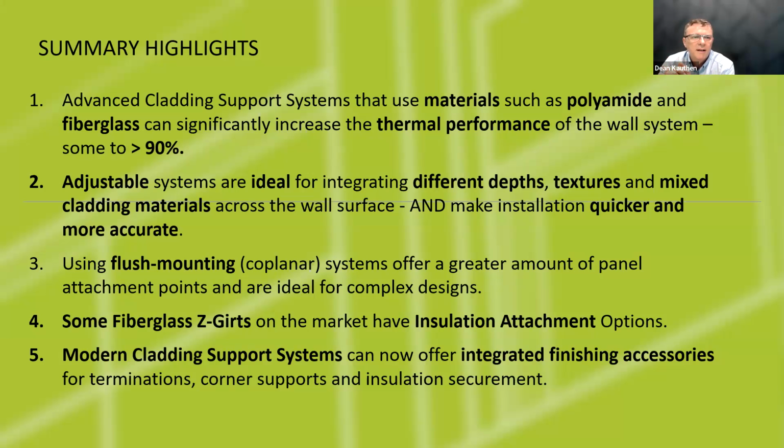in which subcontractors can bid. And using these flush mounted or coplanar systems gives you a great deal of attachment points. They're great for complex designs, but you don't necessarily have to add material across the entire facade. You can add them just where needed. And we know that fiberglass Z-girts have integrated insulation securement options, and you have a wide variety of choices of finishing accessories to help you with your terminations and corners and insulation securement.